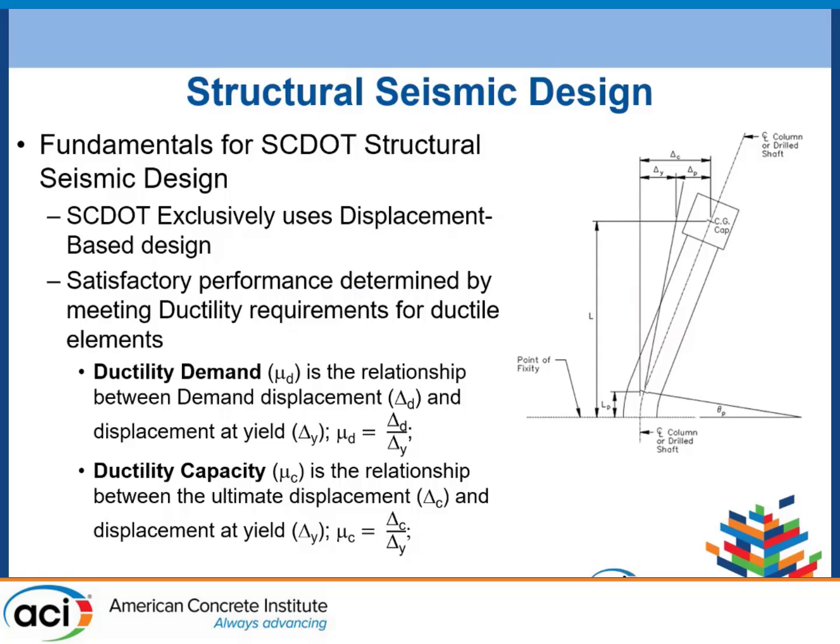And we compare that to how far they move at, say, the point at which a plastic hinge forms. We also consider how far they can move. So at what point does the column or pier rotate so much that it can no longer accept load.